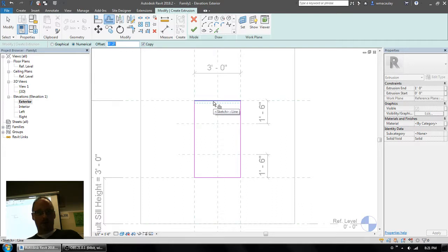So now when I hit tab, I want tab to select all 4 of these pink lines and offset them all at once. Can't do it because my cursor is in the box. So see, no worky. To fix it, click in white space after you've set the value, and now observe, hover to the inside, tab, aha, and now left click, and there we are. So that is our outside window frame created.